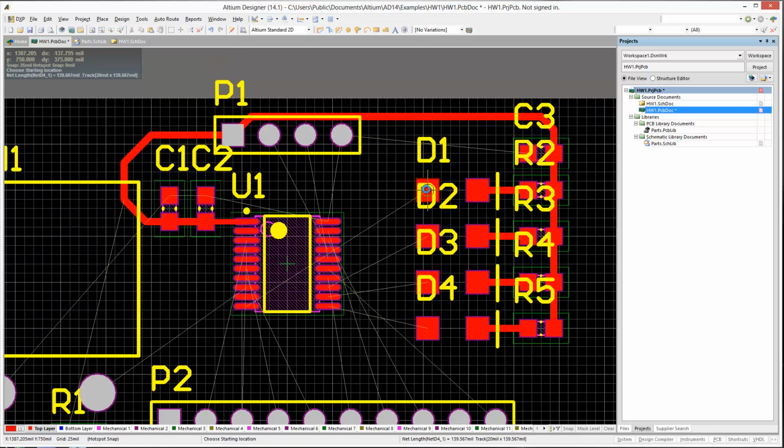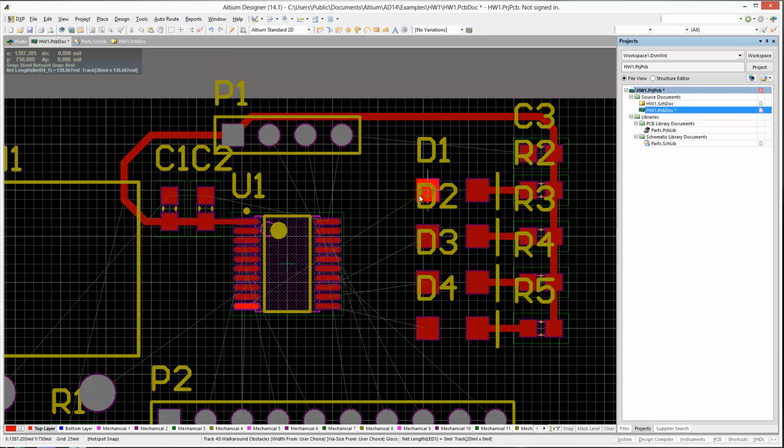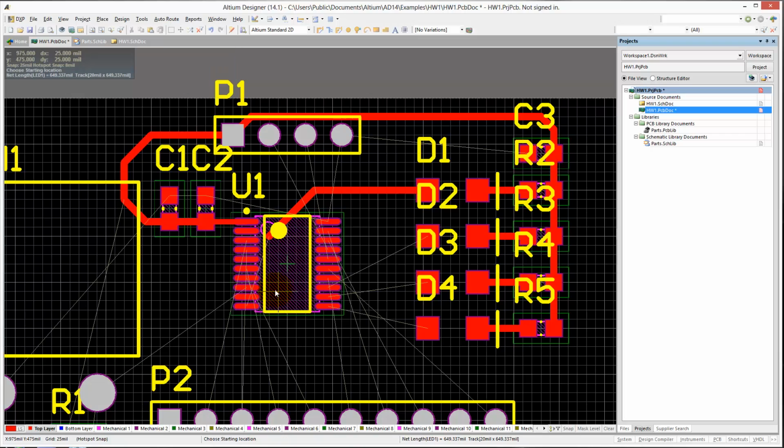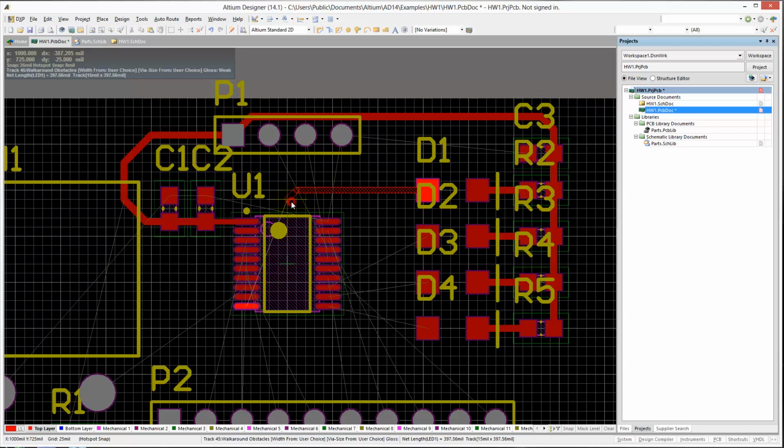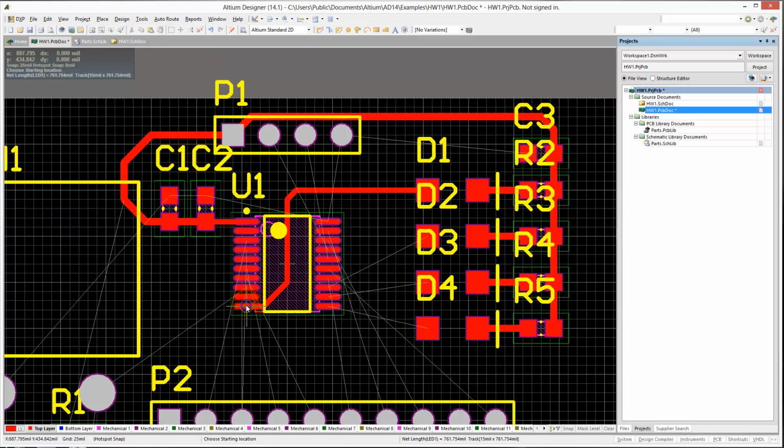And if you notice, I make a connection by clicking left. I can go route it to the trace. In this case, this was actually wrong. I want these to be 50 mil traces. So again, PT, and have this connected. And finishing up your trace is just clicking right.